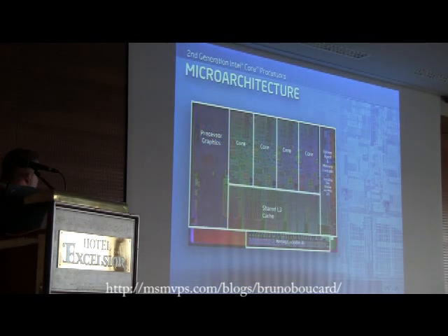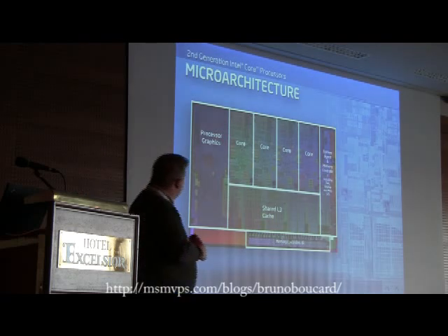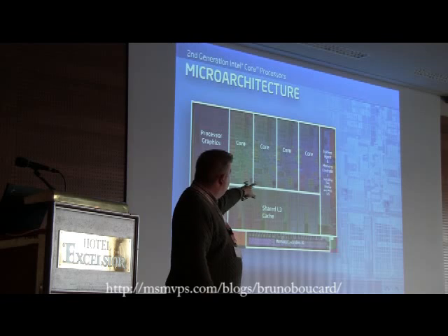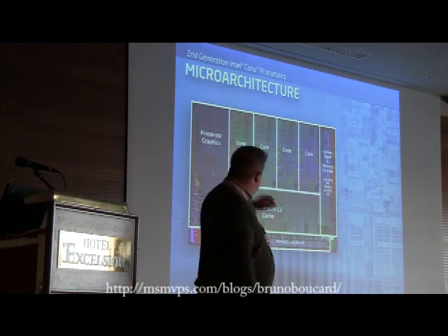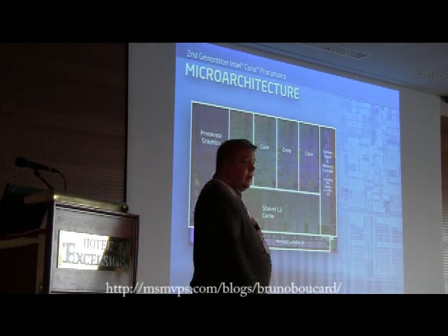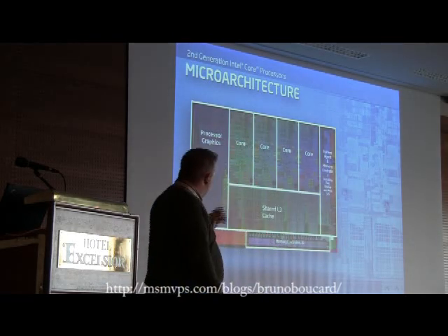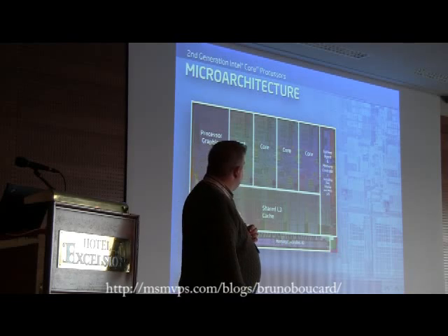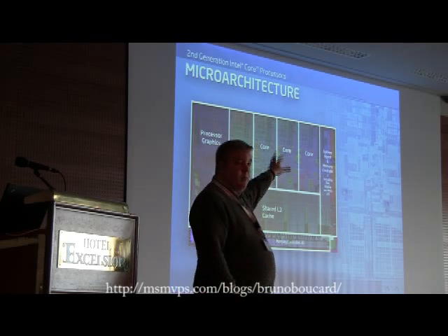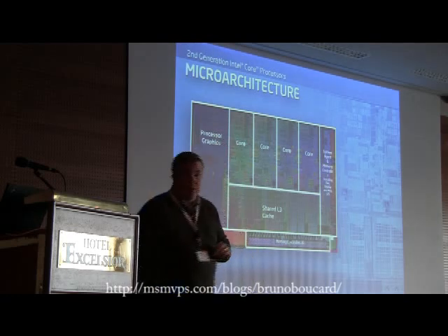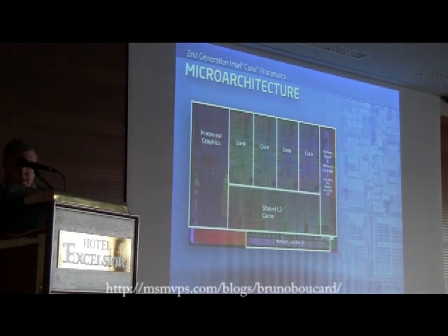Okay, so this is what the processor looks like. You notice you see 4 cores across the middle top, a big shared L3 cache. And then on the right, your left, you see a big huge part which is the processor graphics. Okay? And then on your right, you see a whole bunch of stuff. That is essentially the memory controller and most of what was formerly called the North Bridge. Okay? So most of that capability is integrated into the CPU now. Okay? A little bit more detail.